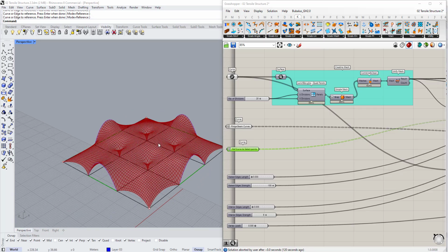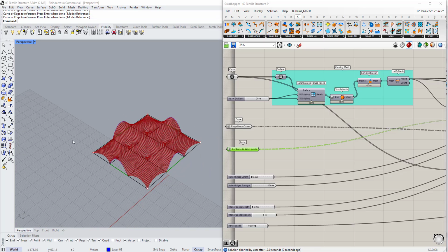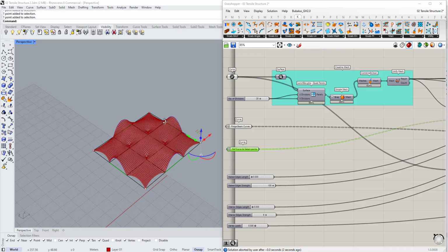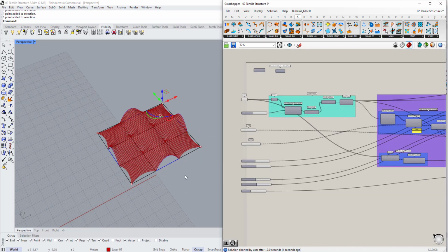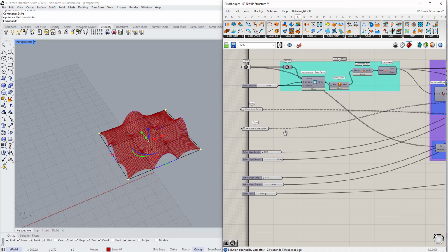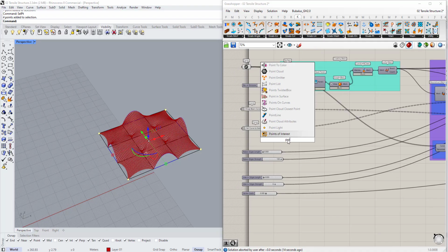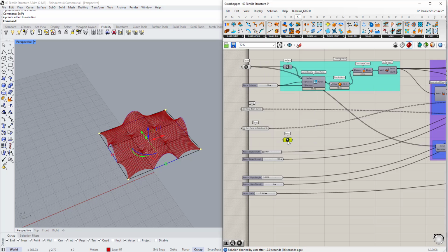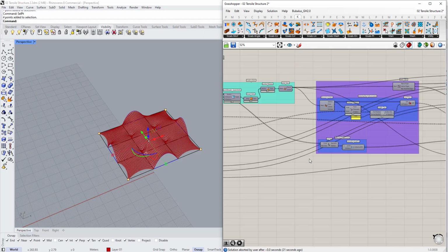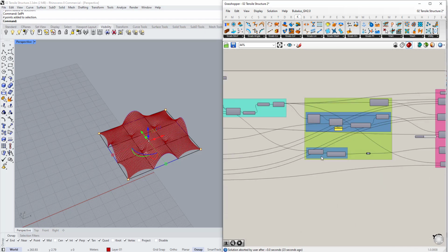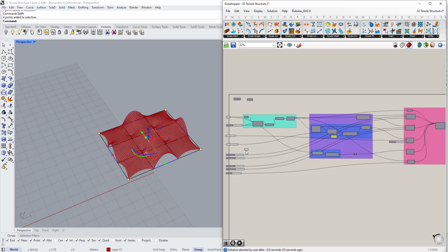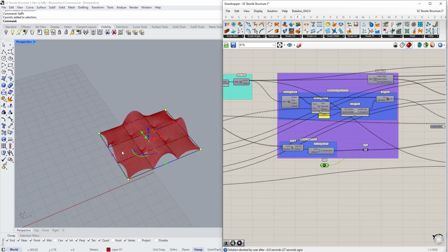As you can see, I want to remove this point, so instead of removing it, I'm going to just place maybe 4 points here. And these are the points that I'm going to use. So type SLPT, select all the points in this view, double click and type points. Right click, set multi points, and let's double click here and place all of them here.